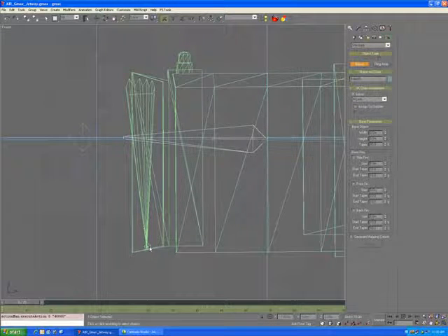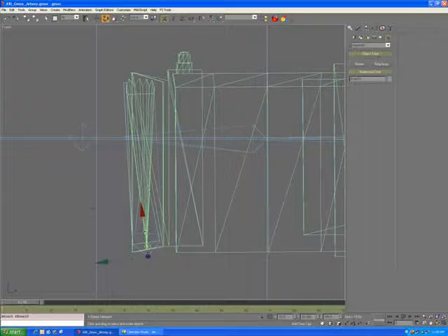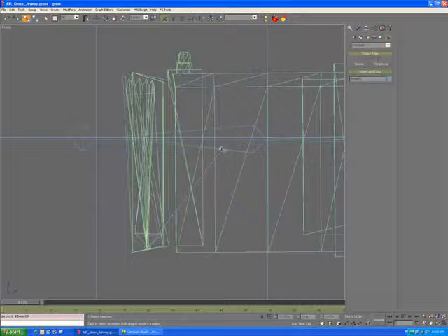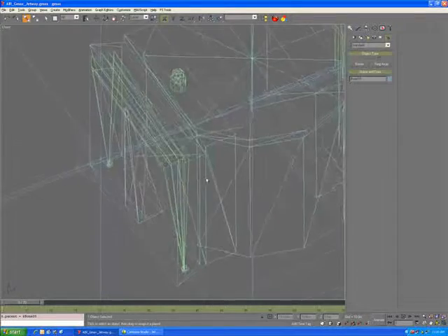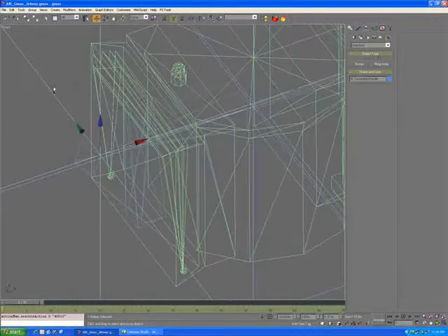Okay, so what I'm going to do now is create 2 bones for the jetway hood. One at the back of the hood, and then one at the front of the hood. And we'll move this one up just a little bit here. There we go, so that it lines up a little better. We're going to link these bones to that bone there. That way they will follow. If this IK handle moves, they will follow along there.